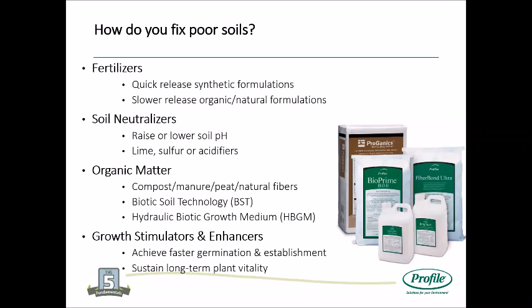Next, how do we fix poor soil? So we got the results. How do we fix them? The most common one I see on any of our erosion control plans is typically your fertilizer. You're going to be applying that anytime you put down seed. There's a variety of fertilizers. There are quick-release synthetic formulations, but also slower-release formulations as well. You can have a coated type of nitrogen source, something to really delay and feed the plants more slowly than that direct hit of a synthetic fertilizer. There are also organic and natural formulations that I typically prefer on most of the sites I work.